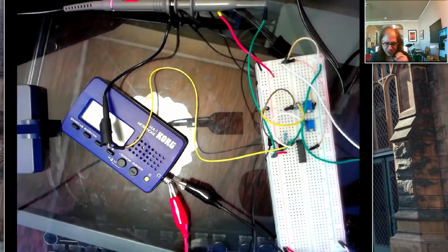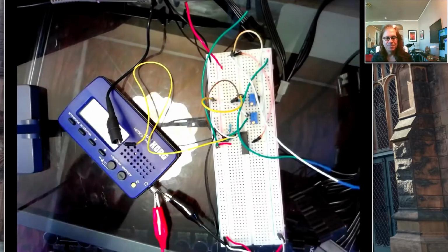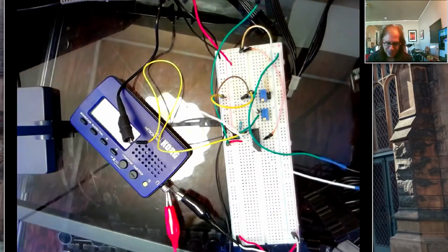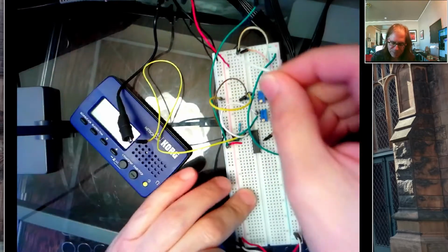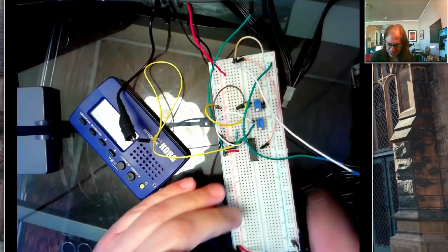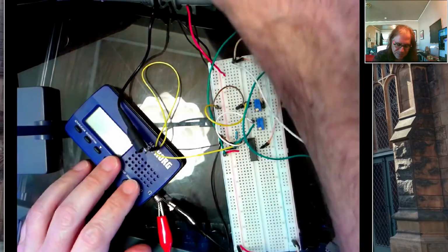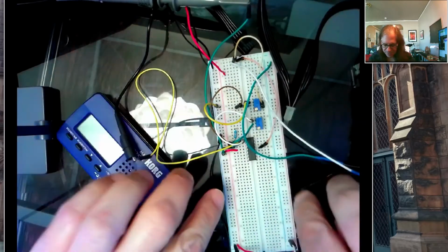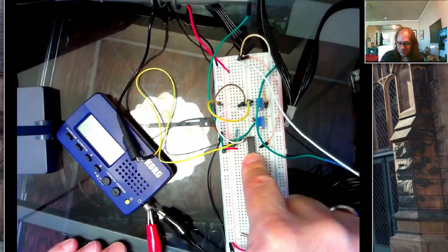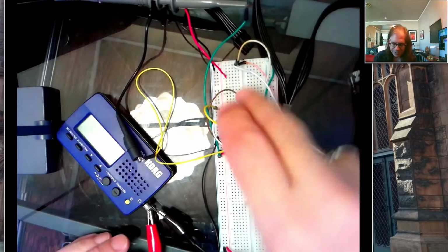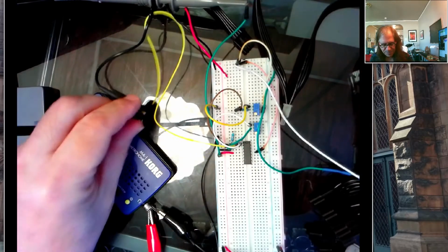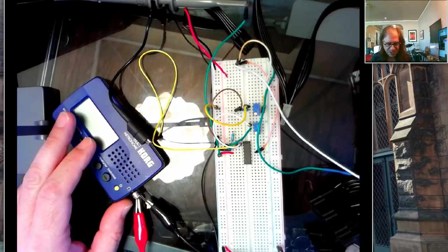And so this is pretty simple to hook up. I have a nice new PC power supply. And this is mainly giving me negative 12 volts over here, positive 12 volts on my rails, and then ground coming in here to my ground rails. And this is an op amp. This is an LM324. And then these are two variable potentiometers, and it's just the circuit that's presented on paper.